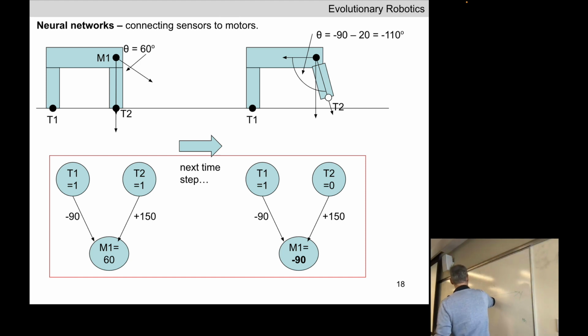So let's imagine we place a bunch of links in our physics engine to make up the body of the snake. I'm drawing these links as separated from one another, but let's assume that these pieces are all touching. Let's assume that I create link 0 here, link 1 here, link 2 here. I attach a joint here, 0_1, that attaches link 0 to link 1.